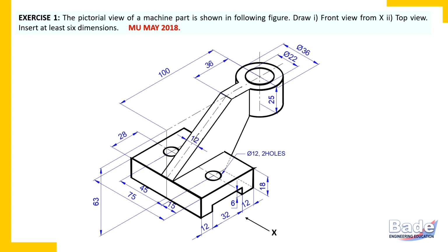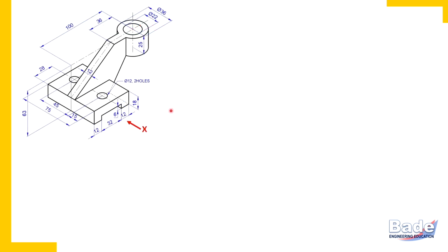You will understand. Now, first thing what you are going to do is identify orientation of length axis, width axis and height axis. These are the 3 axes. Of course, vertical axis is height axis, and now we'll have to decide out of these 2 axes which are at an angle 30 degrees with horizontal. Parallel to this arrow, that is width axis, and of course the third axis is length axis. Now we'll be able to identify overall length, width and height.